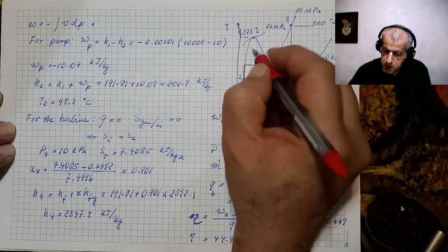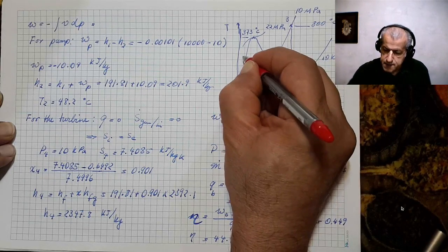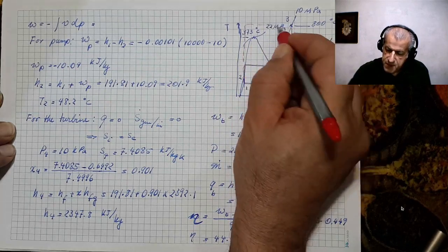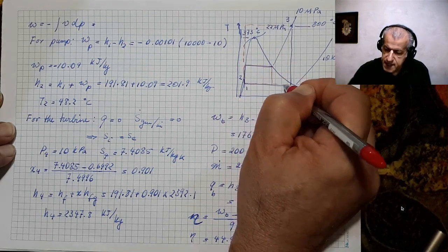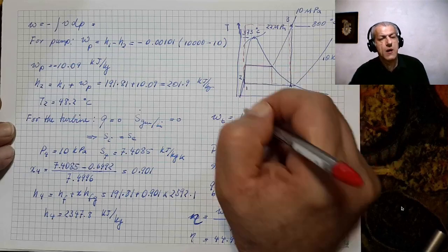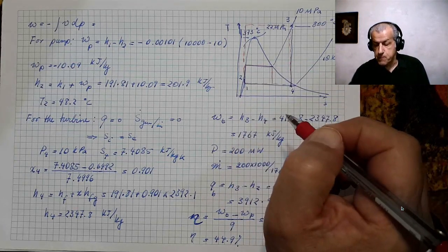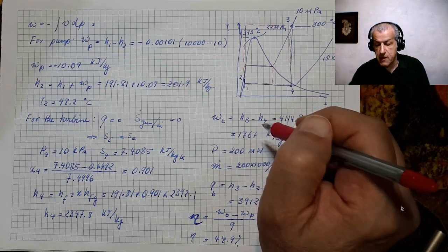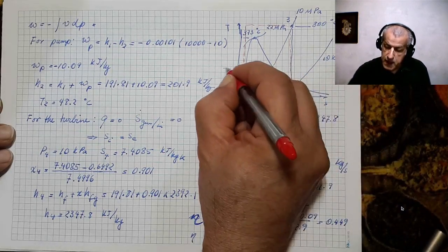And the other would be a Carnot cycle which is between these lines, depending on if you assume the hot temperature for this cycle as 800 or if you assume it to be T11, which is the saturation temperature for 10 megapascals. And we would get two values.